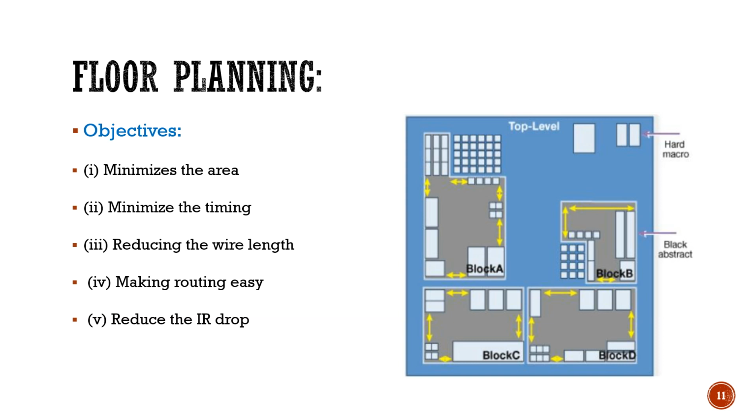When we are constructing a building, we used to prepare a floor plan, right? We simply draw a sketch for a particular land area, and we will be deciding how much amount of space can be allocated in a room. Similarly, here what we are going to do, we are going to draw a rough sketch of how to place the components close together in such a way that area, timing, wire length are getting minimized. That is what is carried out in floor planning.